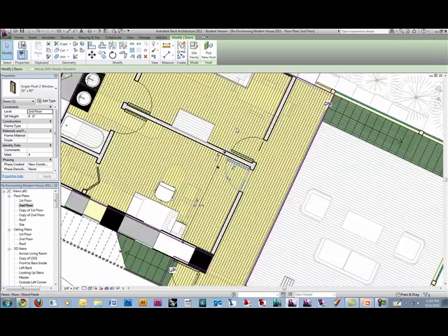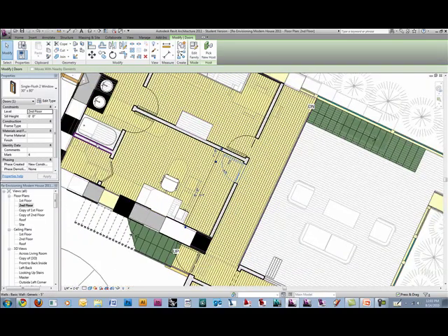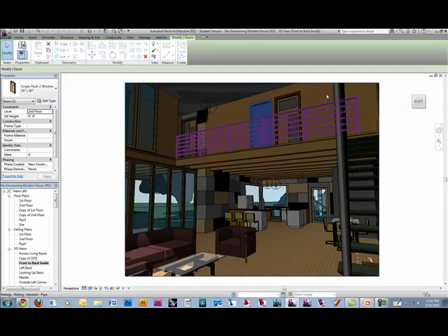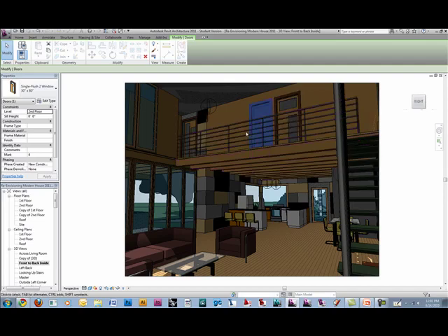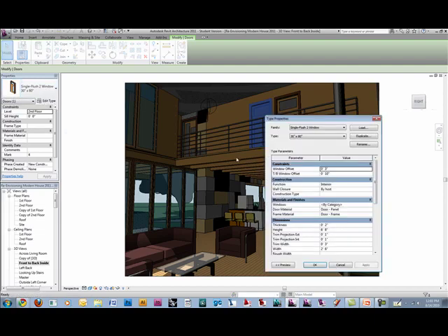Because we made those parameters, now we could also change the materials here in the project without having to go all the way back out to the family. Yeah, let's actually do that real quick. So maybe I don't like the door material. Maybe I don't like that brown because the wall looks like it's a tan color anyway, so that'll look kind of crappy if I did that. Brown on brown. So make sure we have the single flush 2 window door selected. Go to edit type.